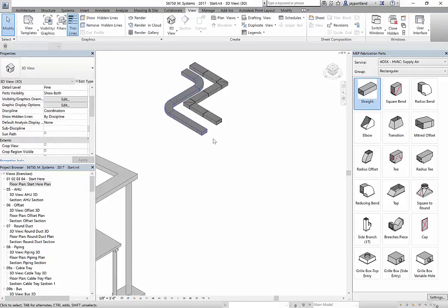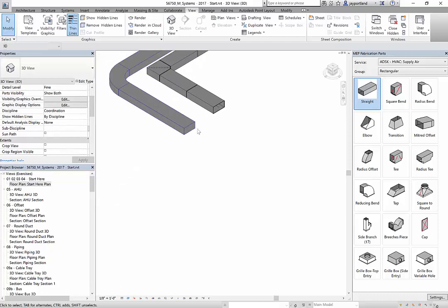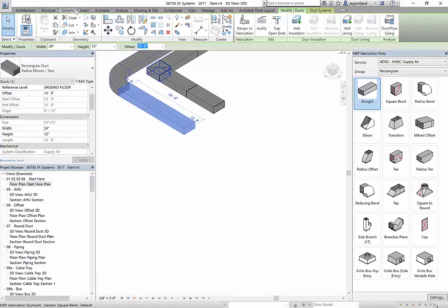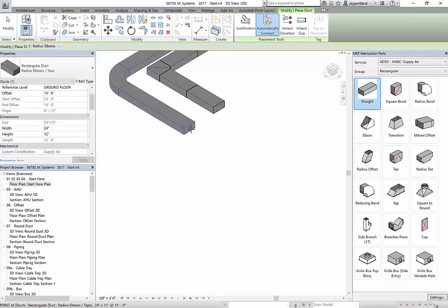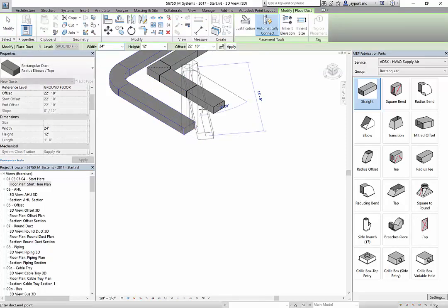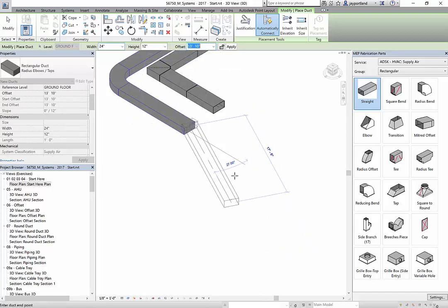Okay, so we're at the same elevation here, and what we'll do is I'll just continue adding more ductwork here. And what you'll see is that it snaps to the center point, but as I draw that, let me just make sure I'm at the right elevation, 13 feet. And hit enter. It's doing the justifications at the top. So this should be 13 feet, I guess 10 inches. There we go. Or 13 feet 6 inches.